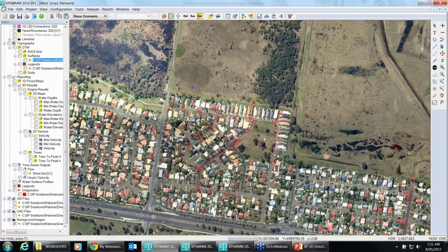I typically say to most users on this side of the hemisphere that as you're going through a model, one of the starting points is to always have a good aerial photo. Aerial photos put us into frame straight away, particularly if they can be geo-referenced. The next core thing is our subsurface infrastructure: those pure 1D elements, the pipes, inlets, outlets, head walls, etc. These days, often they can be picked up from GIS databases, whether or not your local authority has that publicly available, or alternatively, you may need to engage a surveyor to pick up those points.